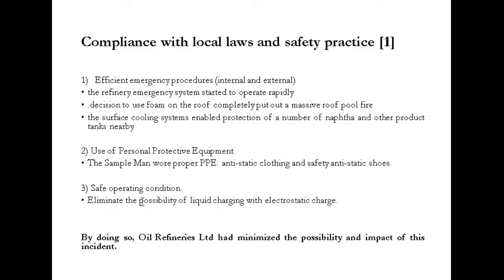Secondly, we can see the sample man wore proper PPE, which includes anti-static clothing and safety anti-static shoes. Thirdly, the process was held under safe operating conditions. This could eliminate the possibility of liquid charging with electrostatic charge, which is done by waiting for the liquid movement during filling for almost 10 hours until sampling was done.